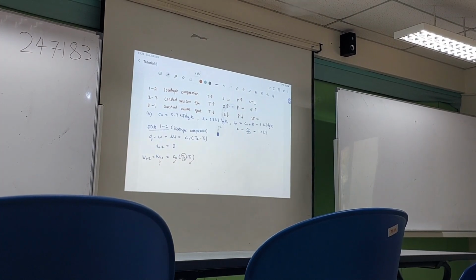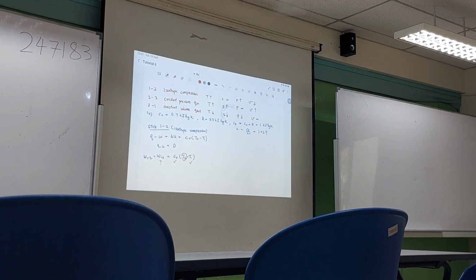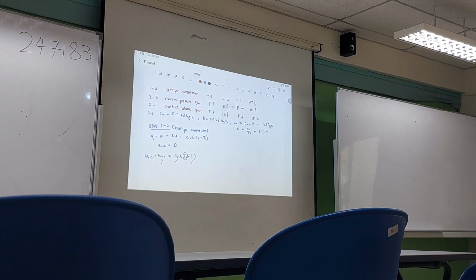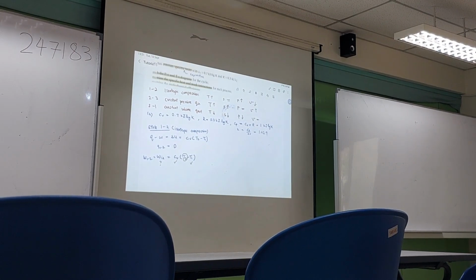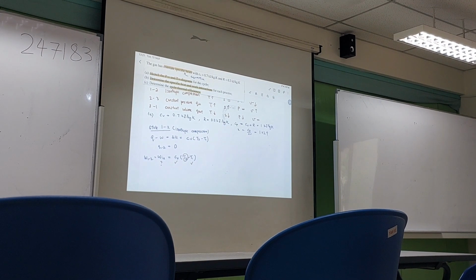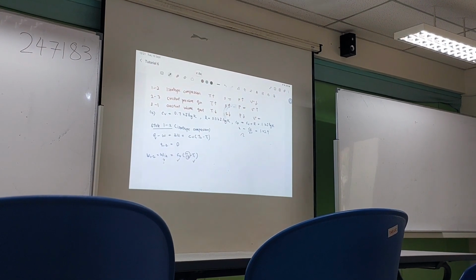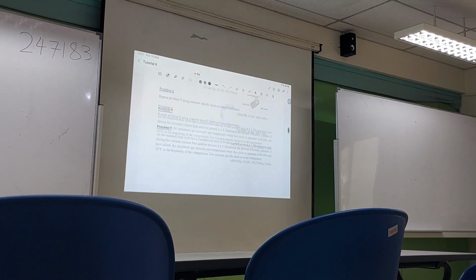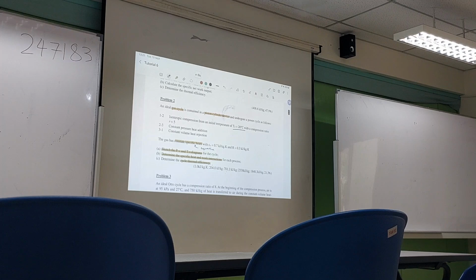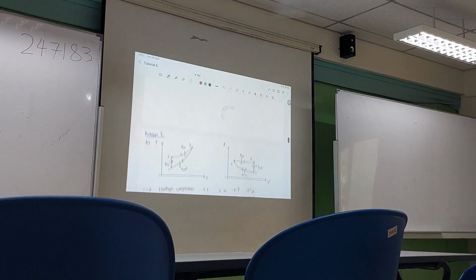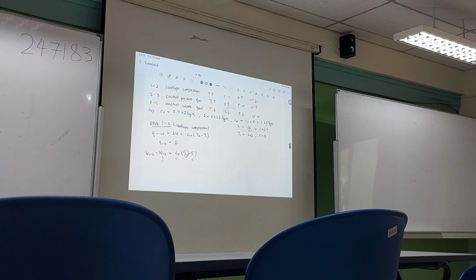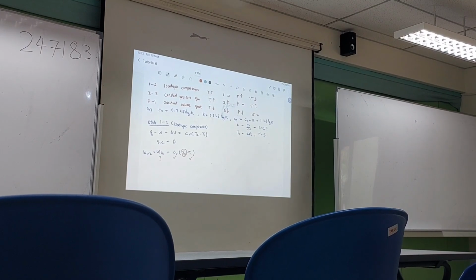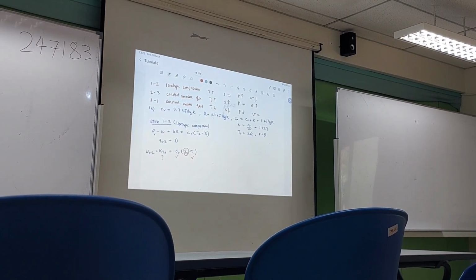So how do we find T2? What are the equations that you can use here? Not quite. Okay, let me note down more information that's given by the question. Okay, no, it's not here. We know that T1 is, let's go back, we know T1 is 20 degrees Celsius, compression ratio is 5. If you say ideal gas, how would you use ideal gas? Yeah, you need to use the isentropic relation actually.